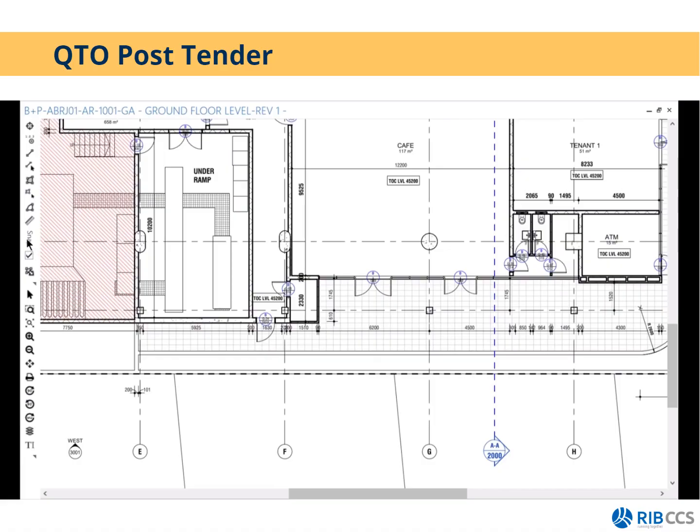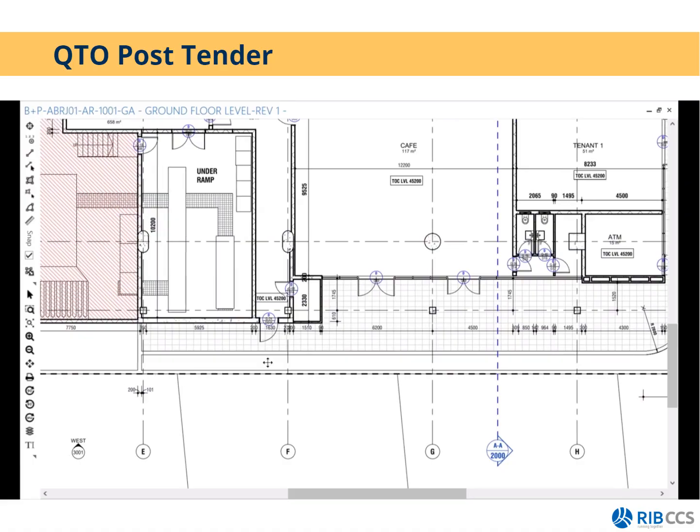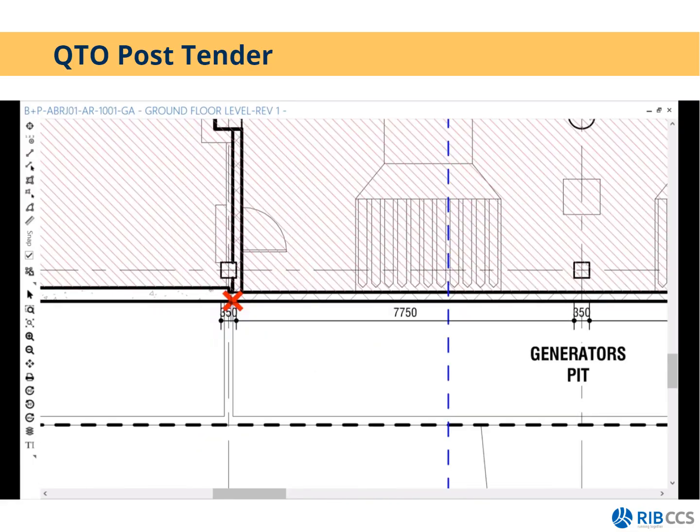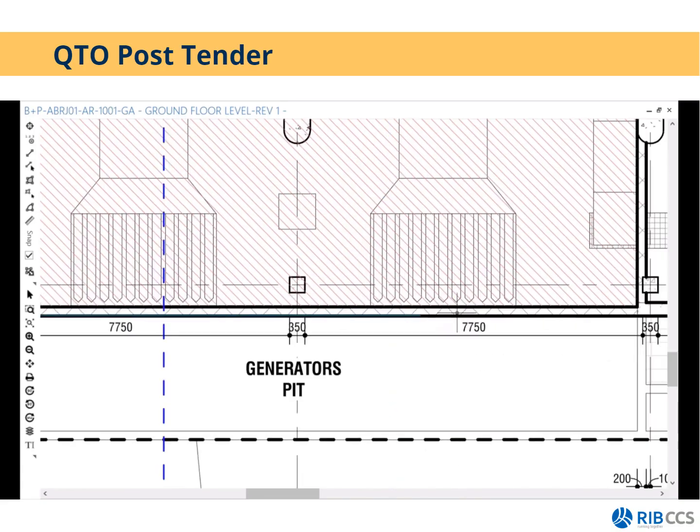Then I'm just going to detach my drawing to explain to you the drawing tools, because otherwise I can't see all of them. So the first drawing tool is the snapping tool. If I take my line tool and I click, for example, where this measurement on this wall would start, I have that little X. The system will automatically follow this line on the PDF. So even though my cursor is over there, my measurement is on that line. And we call that geometric points. This is to make your measurements a bit more accurate. But if you would like to go here, for example, I can turn my snapping off using that tick, and then you'll see my line will follow me in any direction.